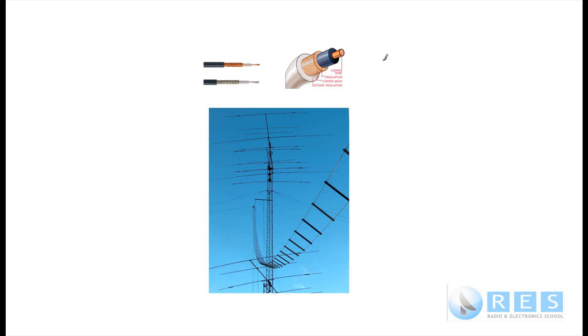However, a coaxial line does not withstand standing waves very well. When you have standing waves, you have greater voltages and currents than you would normally have, and with coaxial lines, the presence of standing waves can significantly or even greatly increase the line loss. With parallel line, on the other hand, the SWR and standing waves is just simply not an issue.